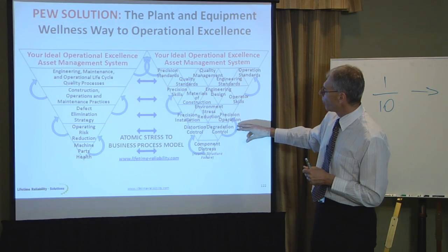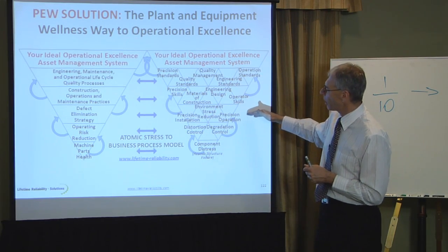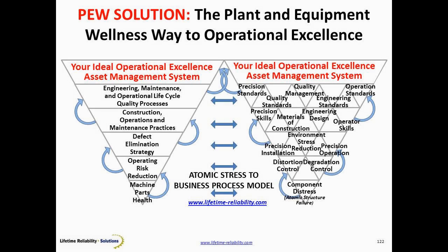And then I'm going to have processes and procedures that involve precision maintenance, precision operation. I've got to control the environment that part is in. If my part is inside of the machine, then the local environment around it, the lubrication, the temperature, the interference fit, the distortion, the overload, I've got to control those, because if the part breaks, then the machine fails.